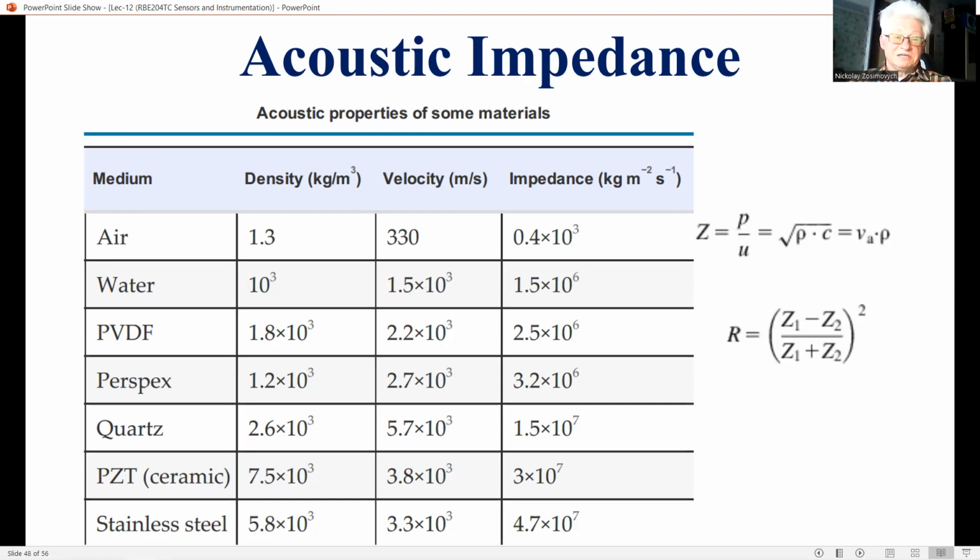And secondly, transmission from an acoustically soft material to an acoustically hard material is poor. This applies in particular for acoustic sensors in air applications because of the wide gap between the impedances of air and most sensor materials. Since many systems consist of a source and a detector, the power loss occurs twice, resulting in a low S over N ratio in acoustic sensing systems.